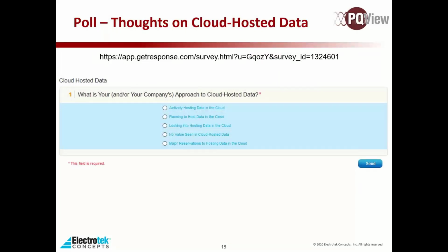A question about what the IT implications and firewall considerations are of communicating directly to devices. Obviously, if we're going to communicate directly with the device, we need to talk to it over whatever port that device uses. For example, Ion meters communicate normally over port 7700, so you'd need to allow communication through your firewall over port 7700 to that device. It varies depending on the device; Dranetz meters are by default port 80.